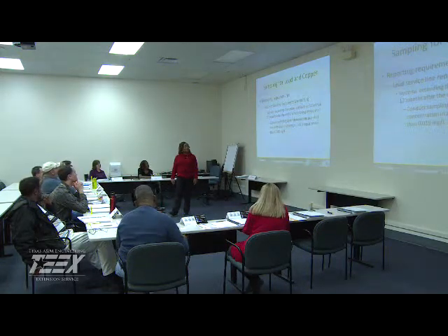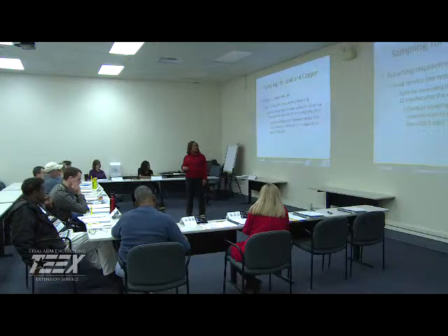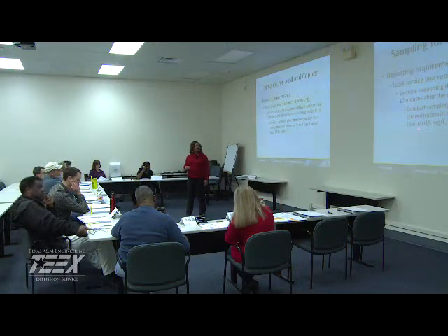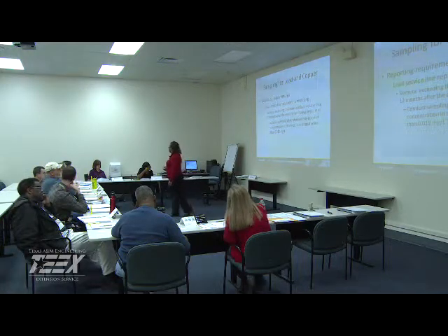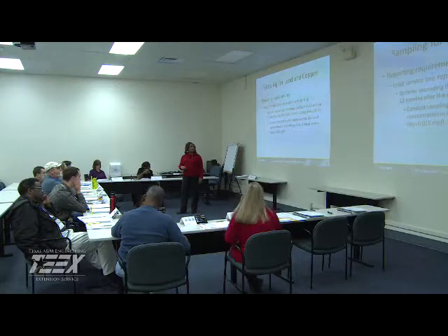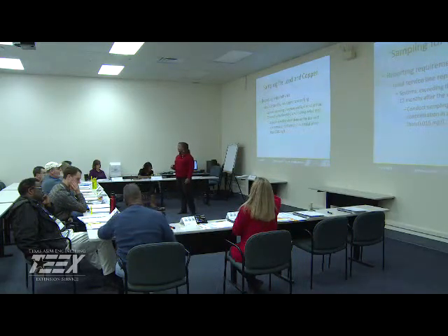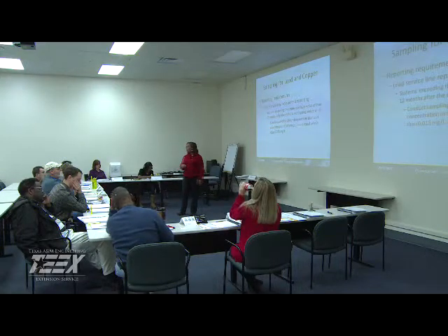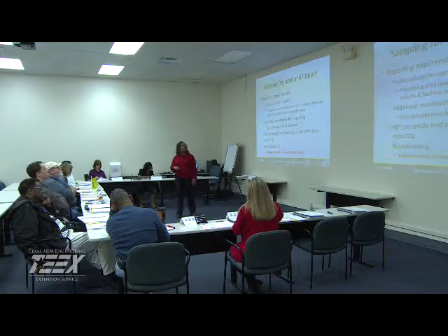All right, if your system exceeded the action level no later than 12 months, again, conduct your sampling and demonstrate the concentration in all your service lines is equal to or less than 0.015 milligrams per liter. Lori mentioned 15 parts per billion. That's just another way of looking at that number, as a whole number as opposed to a decimal. Same thing though.